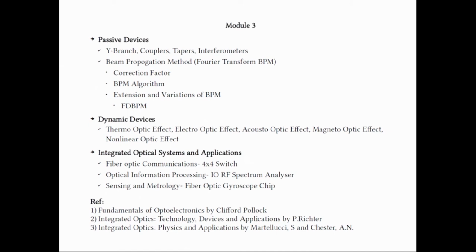In particular, we have observed that lithium niobate is one of the most popular materials, which has a very high electro-optic coefficient. The electro-optic tensor of lithium niobate has many components, but we can choose the appropriate component by choosing the direction of propagation of the light, the orientation of the crystal, the placement of the electrodes, and so on and so forth.